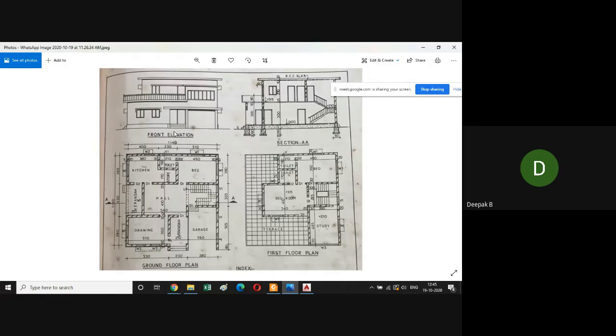So first draw the plan, then project it sidewards and draw the first floor plan, then project it upwards to get the front elevation. You can use the dimensions from here. The next step is that as per how you used to draw the sections in your graphics class, you can simply draw projections from this drawing, from the first floor plan, and also draw projections from the elevation. You will easily intersect these lines to form the different important points in the building.